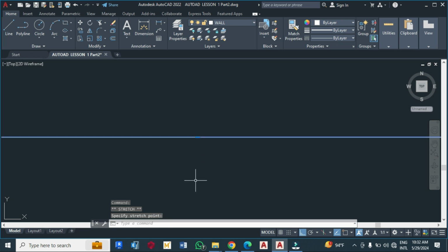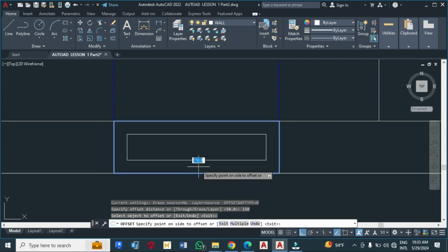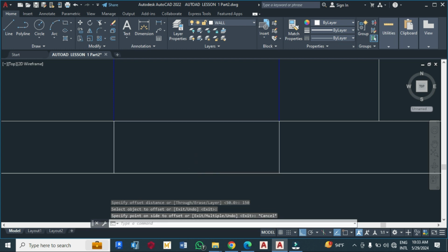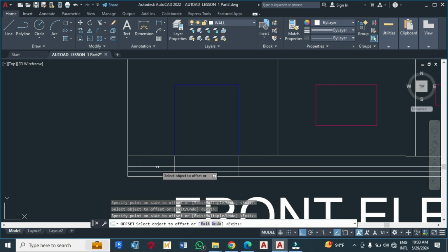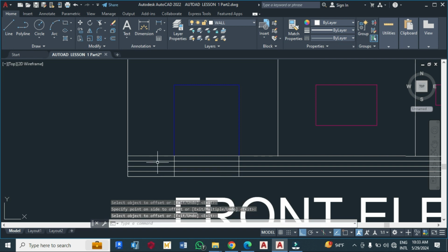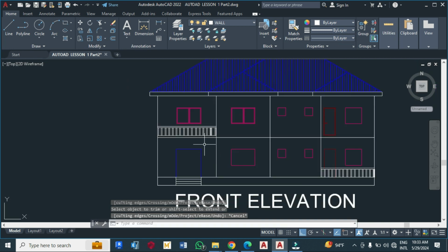Okay, that is, let's use say risers. So I'm going to offset 150. Okay, if I offset, sorry, let's look for a line. Offset 150. If I offset something like this, 150, 150, 150. Okay, then I'm going to trim it off to show that we use that steps to climb up to the entrance. Okay, all right, so that is the entrance.